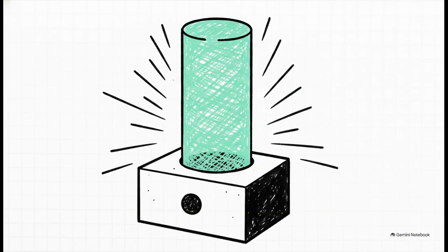But here, my friends, is the trap. When you add a projected tolerance zone into the mix, you completely transform that virtual condition boundary. Instead of a boundary buried safely inside the metal of the threaded hole, our worst-case boundary now leaps upward. It turns into this tall, invisible cylinder extending entirely outside the part, representing the absolute extreme tilted envelope of the installed bolt. It's a total paradigm shift.